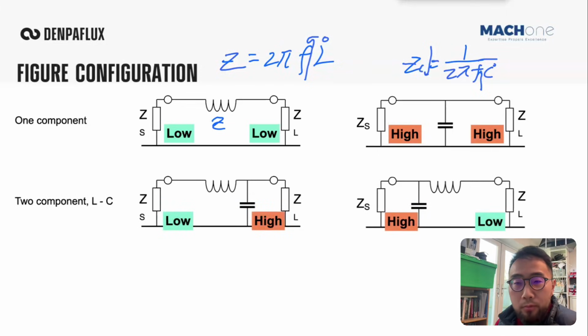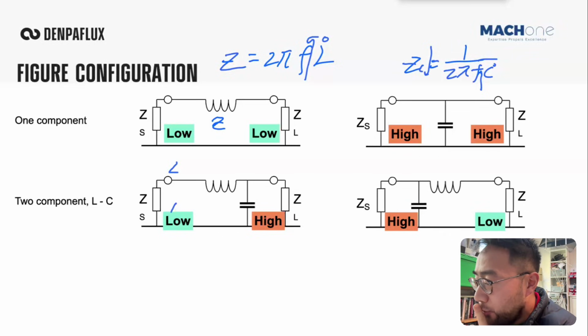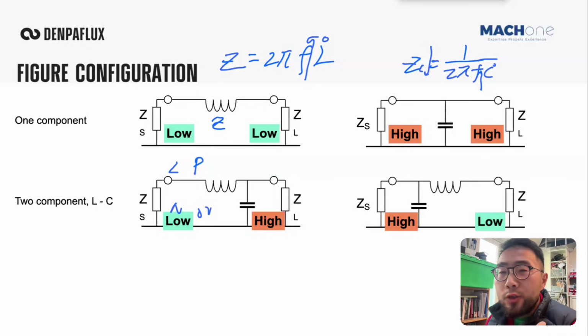But most of the time, people make low-pass filters for EMC applications. So here, again, you have two options. You can either choose an LC filter or a CL filter, depending on your application. In this diagram, what we're talking about is purely differential. When we say differential mode, this could be your live or neutral, or your power, let's say 12 volts and 0 volts, or a CAN bus plus and CAN bus negative. This is the differential mode we're talking about, but the principle is the same for common mode as well, as we will discuss later.